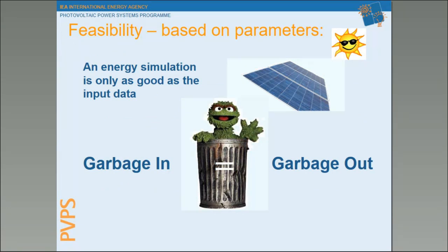In our newly published report, Technical Assumptions Used in PV Financial Models, I do believe that we have explained well how to achieve high-quality parameters. However, the best quality parameter is still accompanied by a variance that can be as high, even more than plus or minus 5%. This variance is a source of risk. 5% on the global radiation in a 10 megawatt plant is not insignificant.